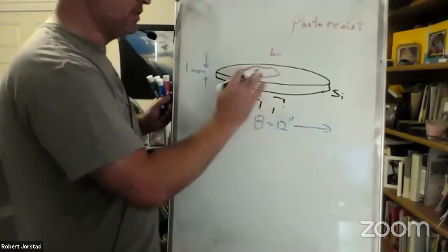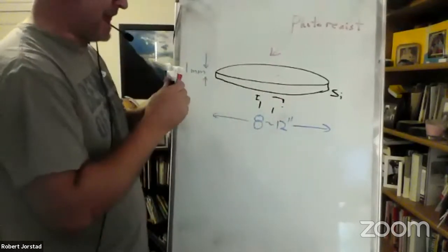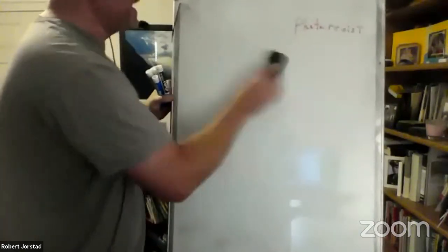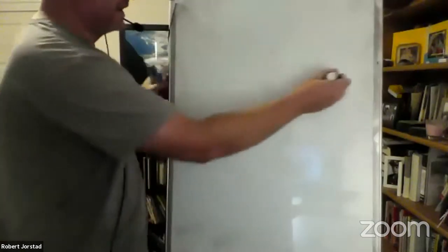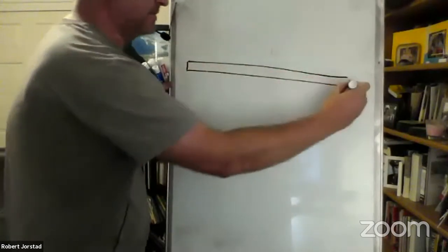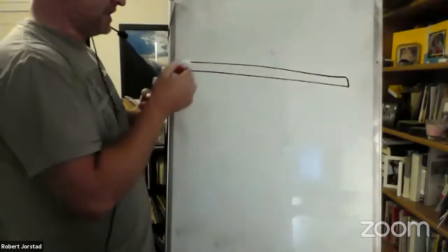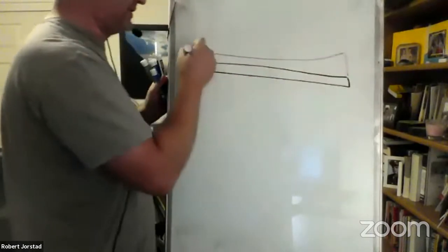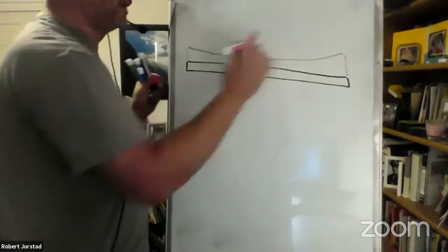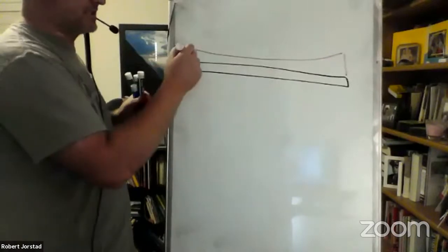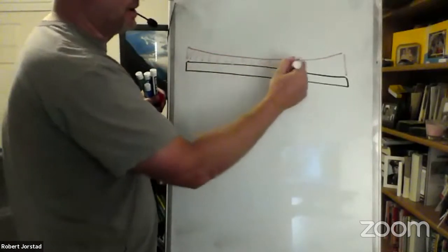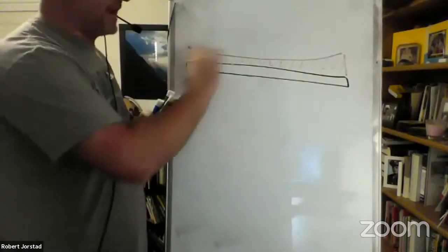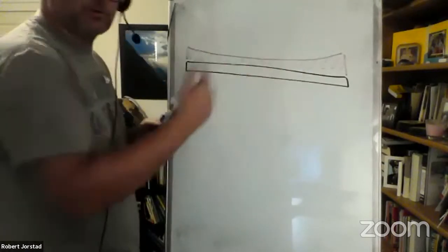All right. When you spin it, you can probably imagine, I need to draw a pure side view now. Okay. When you spin it, here's a side view of the disk. This is going to spread out, just like the water spinner from Physics 161, which you all remember, that was so long ago. You get a slightly thicker layer on the outside, but basically a nice thin uniform layer here. Okay, and this thing's spinning really fast, so you get a super thin layer of photoresist.